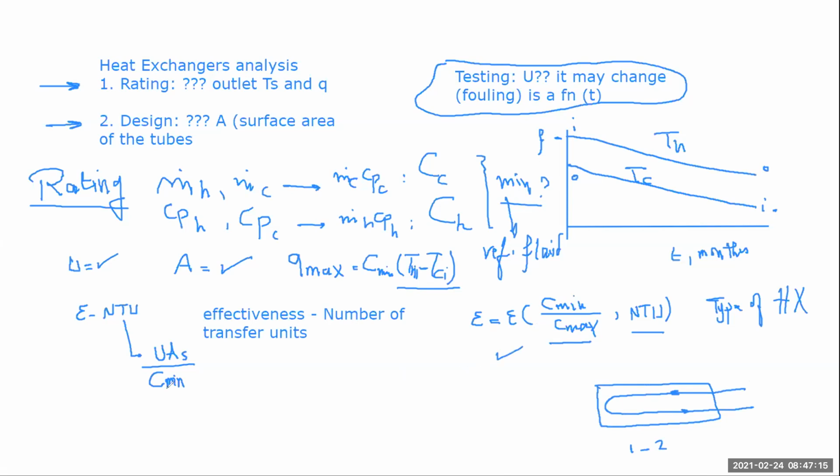epsilon. What is epsilon? After you calculate epsilon, what does it represent? It represents Q over Q maximum. And this is the answer to your question. Q maximum is the ceiling that we can never reach. Accordingly, epsilon should always be less than 1. You can never have a case where epsilon exceeds 1, or even equals 1, because you are not going to reach Q maximum.